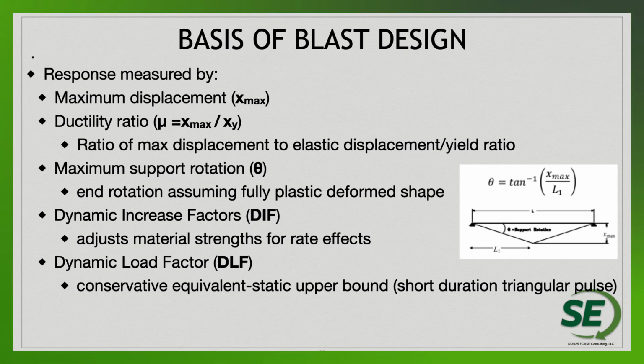We also introduced DIF factors. Those are really important. The dynamic increase factors. We account for strain rate effects. And another very important factor here is the dynamic load factor, usually referred to as DLF, which is used when we idealize the blast pulse as a short duration triangular load.